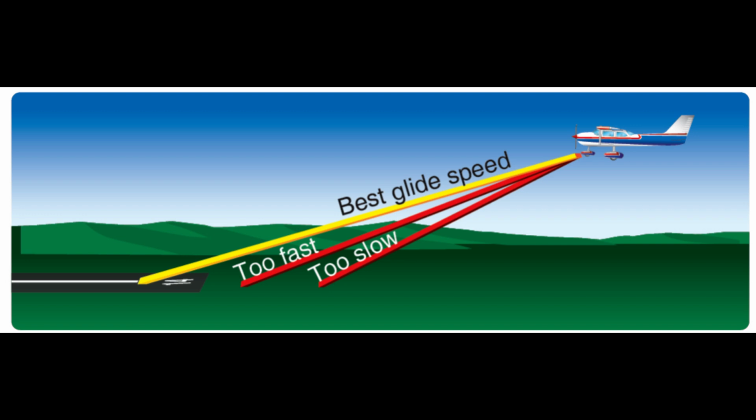Gliding turns. The absence of the propeller slipstream, P-factor, loss of effectiveness of the various flight control surfaces at lower airspeeds, and designed-in aerodynamic corrections complicate the task of flight control coordination in comparison to powered flight for the learner. These principles should be thoroughly explained to the learner by the flight instructor.